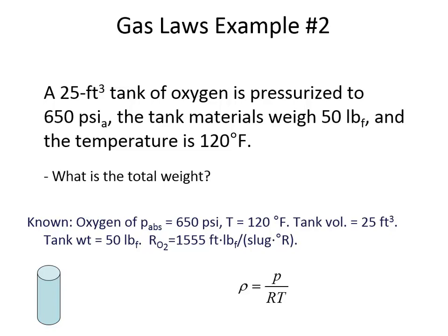So then if we multiply the density by g, that takes it from slugs per cubic foot into pounds of force per cubic foot. So it goes from a density to a unit weight. Sometimes this is called unit weight, sometimes it's called specific weight, gamma. So we know the gamma of the gas, 3.342 pounds of force per cubic foot.